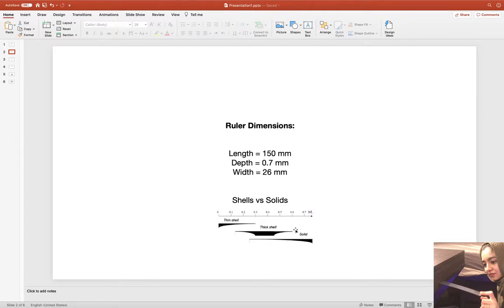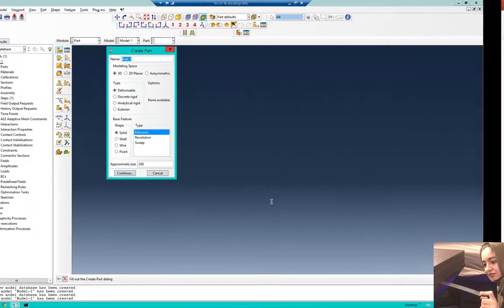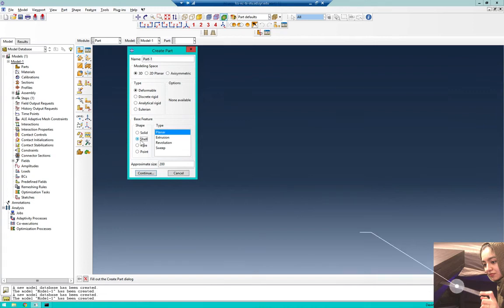If the thickness is so large, you see, when we move here, it means the thickness is large, we use solid elements. However, I don't want you to always follow this. I want you to get the results from shell elements, and then also try solid elements. Compare the results to the theoretical values and see which one makes more sense. So let's use here, 15 centimeters